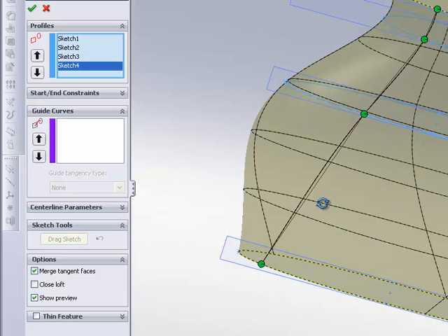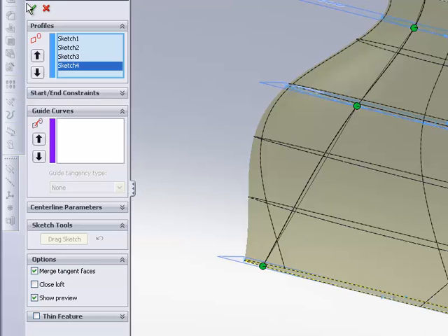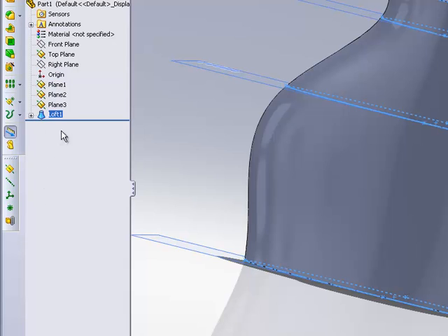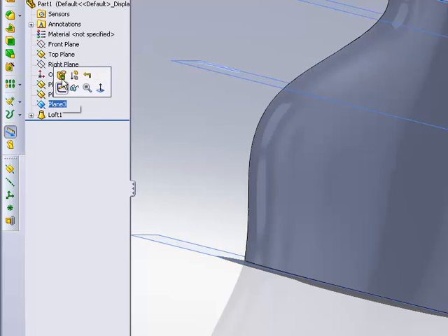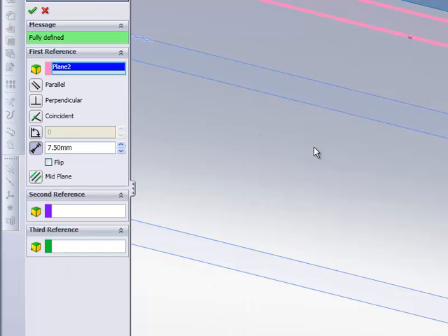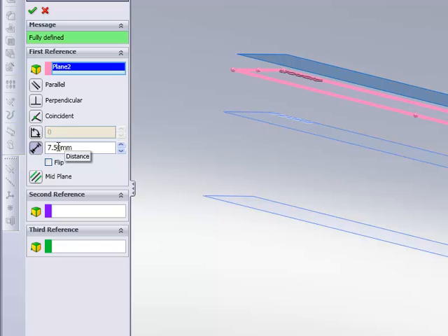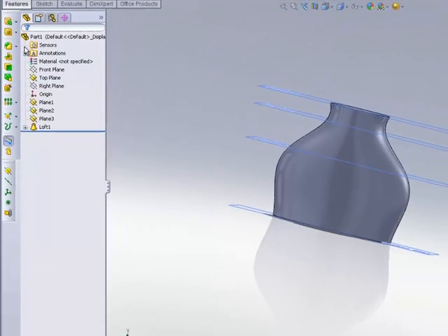So now, just click it, and that doesn't look good. I will be the first to say that does not look good, but click OK, because now we're going to extend out this feature right here. So right click on it, click Edit Feature, and we'll set this to now 10, just to start, to see if that improves it.